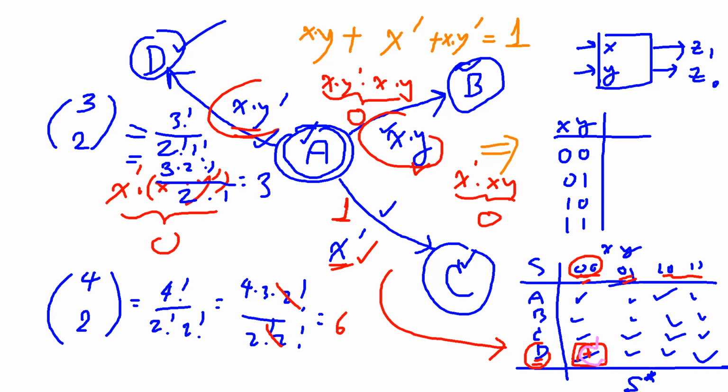So it's easy to check with a state output table. If there is some empty place, it's not okay, or if there are 2 or more next states at the same place, it's not okay.